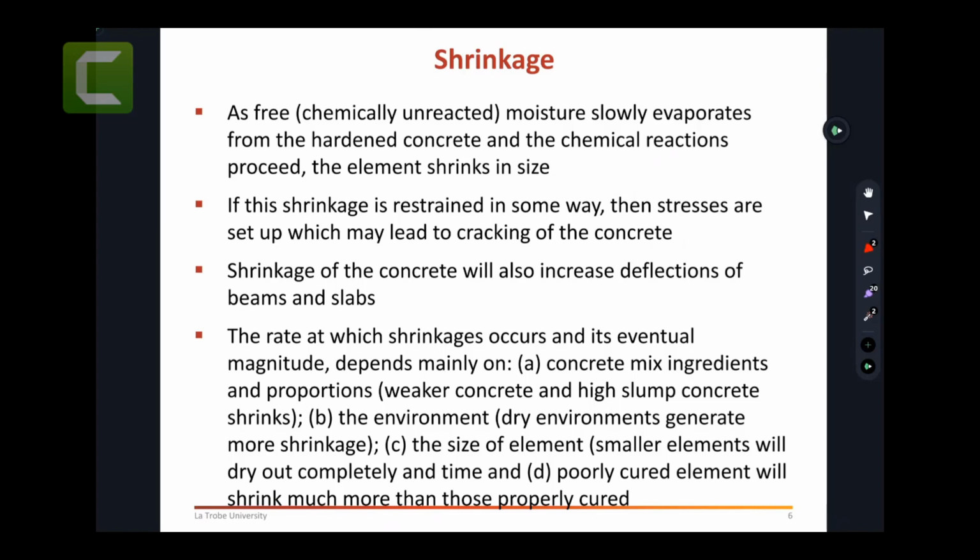Like, quick example, bridges. When they do the bridge, they don't pour it in one go. They make those movement joints, and they are there to allow for temperature and also shrinkage if it was concrete, as well.